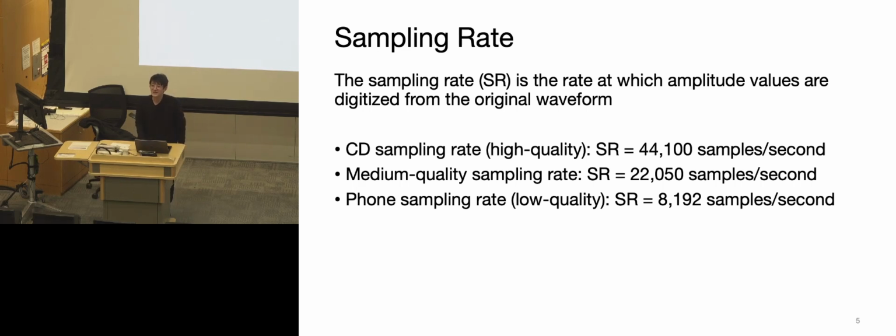Is it less data to transmit over a phone line? Yes. So we have less data, but it's only 8K, and we can still ensure all the data got transferred within this sampling rate. That's one of the major reasons they chose a lower sampling rate, so that given a set bandwidth, we can transfer more data or more people talking.